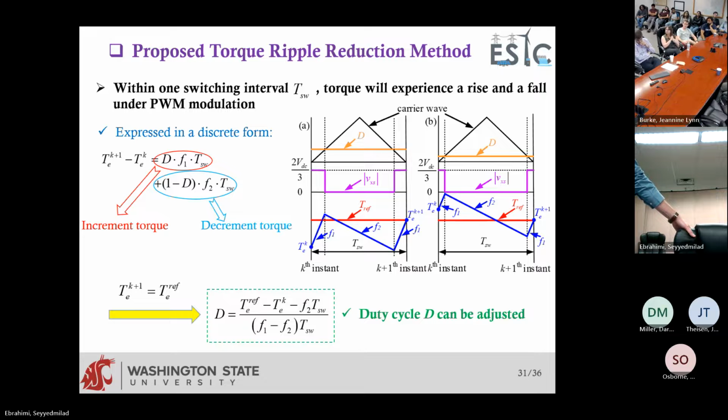Because here we only switch upper leg transistors, and space vector modulation switches all of them, right? We've shown that the effective frequency here can be 4 times higher if you want to have the same number of switchings. So in that analysis, we assume that, for example, the space vector modulation operates at 5 kilohertz. Here, to have the same number of switchings, for fairness, we can operate at 20 kilohertz. We did the comparison, and ours was able to have lower torque ripple.